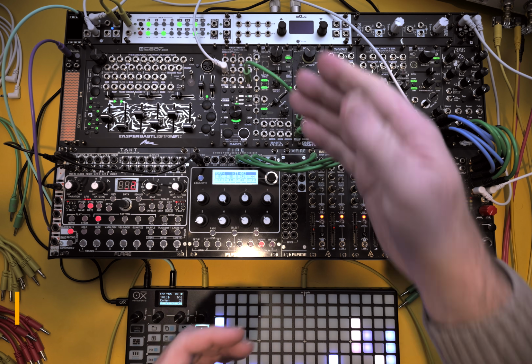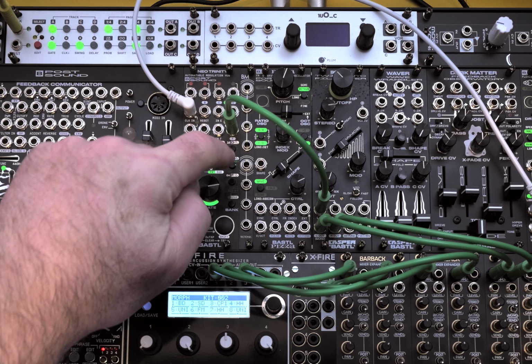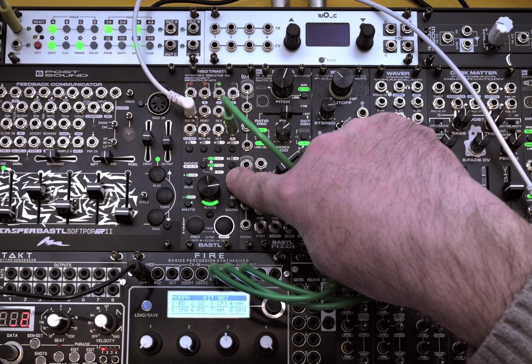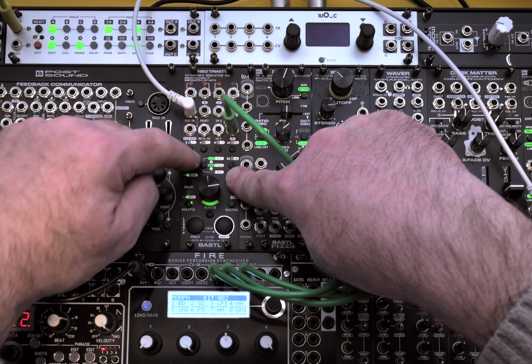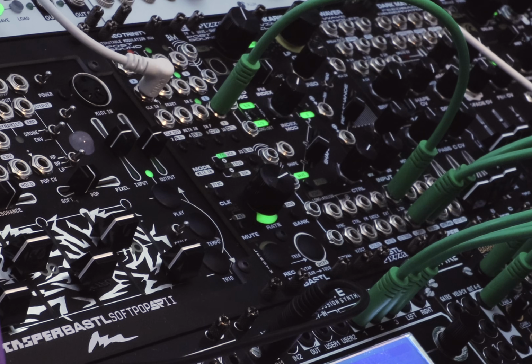Because we have quantizers and envelope generators built in, it actually becomes almost a full synthesizer voice. So what I've done is gone ahead and set channel F to be in LFO mode. Right now, that obviously is just generating a DC offset, so it's not going to be any use to us. But what we want to do is map the input F to be in normal mode, or plus mode as it's called, because then it will adjust the rate of the LFO, in other words, the frequency of the oscillator, based on the voltage there. Great. Now we have a volt per octave input for our oscillator, if you will.